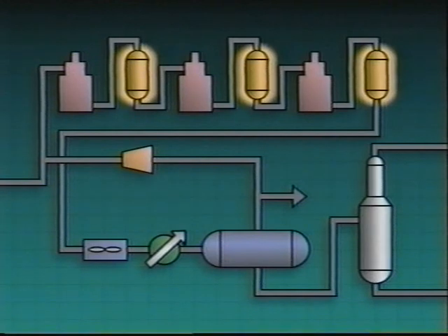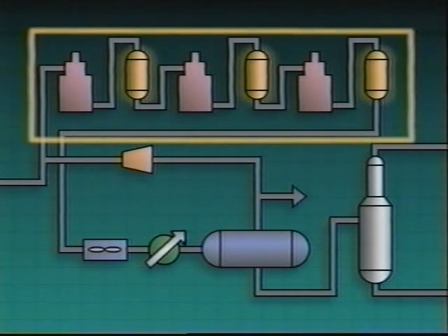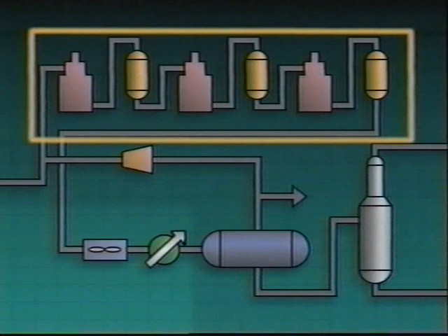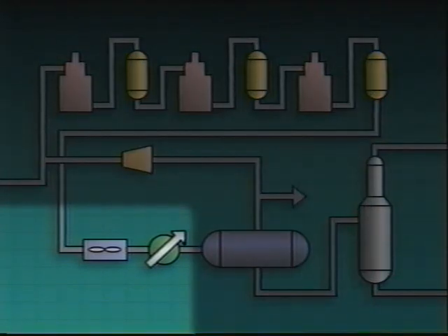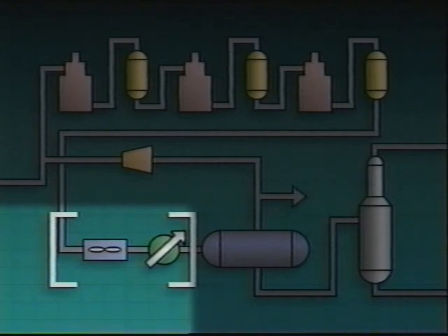All reactor temperatures are normal. In addition, the operators investigate the other process variables in the reaction section, and all indications are normal. This means we can rule out the reaction section. So at this point, we've effectively bracketed the problem within the condenser section. The problem could be either the fin fan condenser or the shell and tube condenser.